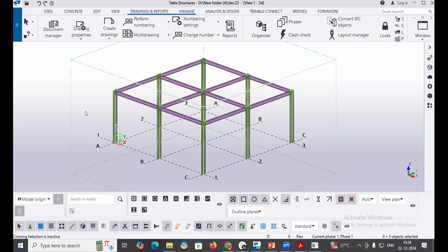But creating the roof sheet here will take time, because for a complete set of plate profile you have to redraw the profile and create it. And for different types of structures, you can't make it as one long pattern. You have to break the complete set of components and create it as a separate custom component. It's a tedious one. But instead of roof sheet, you can create purlin. Purlin profiles are available, so no issues in that. And purlin connections also you can give, even customized connections you can create and provide, no issues in that.